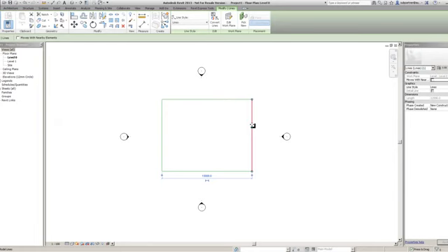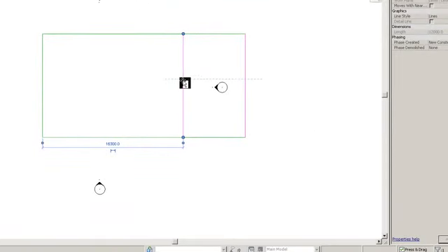Now, yes, it is the move icon. However, it's slightly different. It's what we call press and drag. It's just dragging and dropping things around my screen. So all I'm going to do now is left click and move. I'm just dragging it. You can see I'm dragging it in this direction just here, even if I move my mouse up and down. It's basically what we call constrained. It's constrained by this line and this line. They're basically saying, right, yeah, we'll let you go in that direction. We'll stretch with you, but we're not going to be so accommodating that we're just going to go wherever the heck you want to go. So we're just going to stretch in this direction.